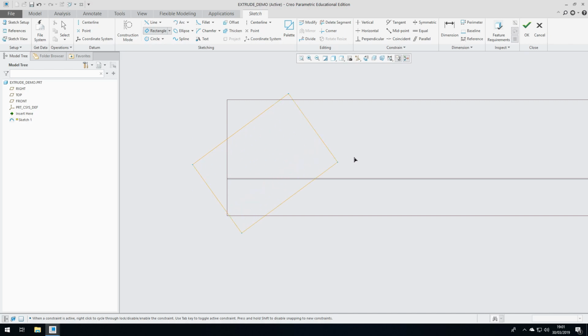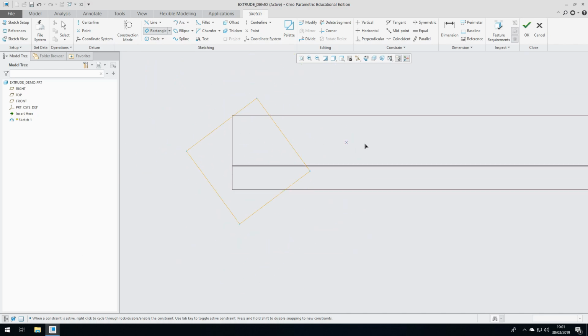Slanted rectangles work in the same way. So you select effectively your axis that you want to work on, so anywhere between 0 and 360, and then you drag the rectangle out from there. This can be useful, but I tend to sketch these parts in after I've drawn the original features, but again, different strokes for different folks. And exactly the same with the parallelogram. It works in a similar way to the slanted rectangle, but obviously produces a parallelogram. Right, so that's the rectangle function.